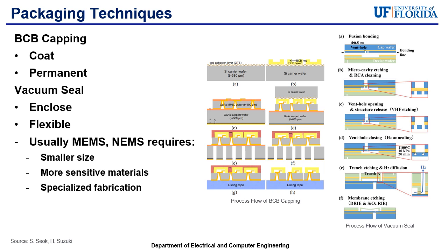First begins with an anti-adhesion layer coating in part A before BCB caps are formed in part B. Next, MMIC wafer bonding occurs to support the wafer in both parts C and D, which is then a support wafer is perforated in part E. In part F, PMMA sacrificial etching occurs, followed by BCB capped MMIC on the dicing tape, occurring in part G. The BCB capping is finished off with the dicing of MMIC.